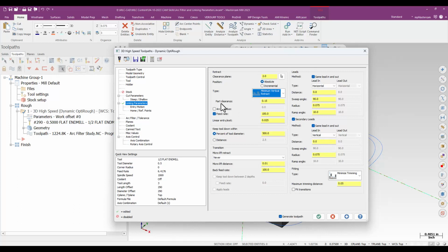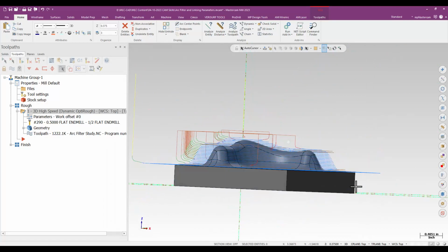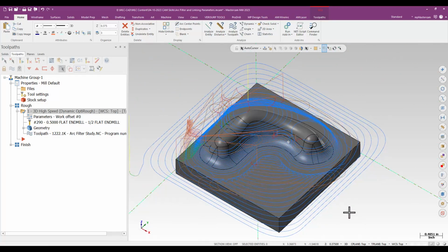So that also gives me an option if I'm feeling confident that it's going to be safe. And again, I can set that feed rate to whatever output I need as far as how quick it needs to happen. I can start thinking about bringing that part clearance a little bit closer, and that is just a matter of comfort. So instead of 150 thou, I'll bring that down to about 75 thou. Again, just trying to cut a little bit of that distance out of there. I'll regenerate that and see what this looks like. You can see, yep, just bringing everything that little bit closer.